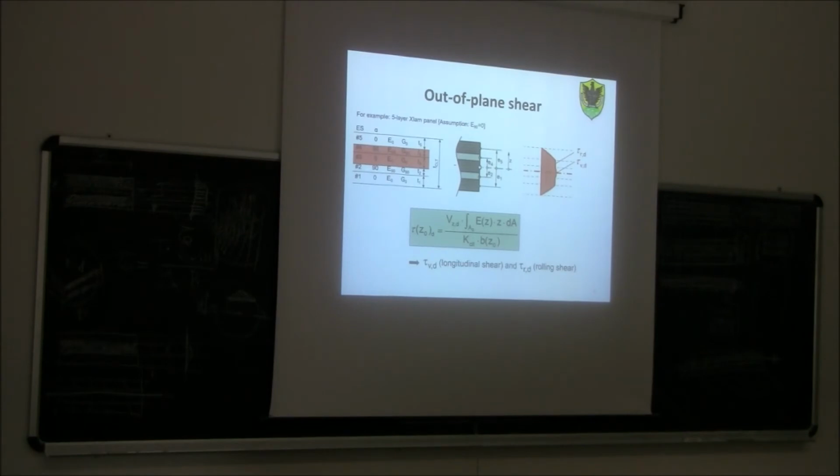So, any question with longitudinal shear, rolling shear? It's a bit, as you can see, it's very simple to get confused with this. You need to remember that one thing is the cross section, one thing is the longitudinal cross section. The two are opposite in some way. But to understand if there is rolling shear or longitudinal shear, we need to take into consideration the longitudinal cross section, not the transversal cross section, where we usually draw the stress distribution.